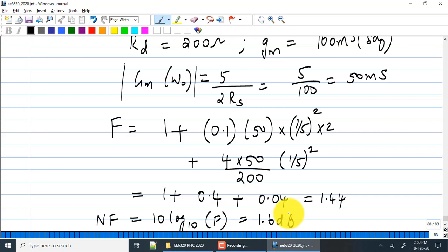If omega t was larger, what do I mean by larger omega t's? For a given GM, you have a smaller capacitance for the device, which means as the process scales, which happens automatically for you, the effective maximum FT that you can achieve with the process only increases. For a given current consumption, for a given GM, you can get even better omega t's in faster processes.